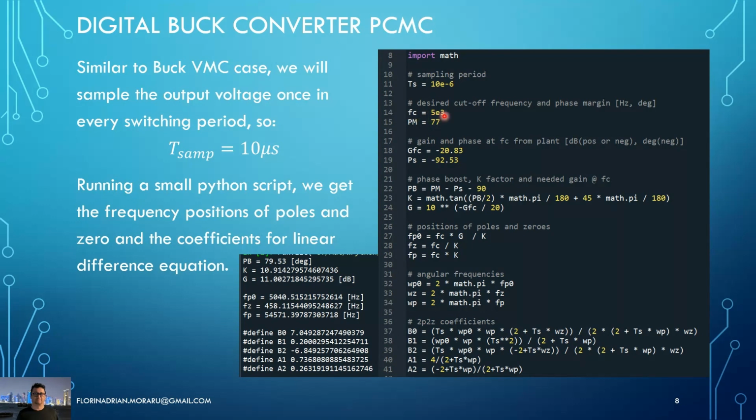And then we want a 5 kilohertz cutoff frequency and a phase margin of 50 degrees, but taking the worst case scenario with phase erosion. We saw it was about 9 degrees from the sampling and reconstruction process, and if we have a complete period time delay, then we have an additional 18 degrees, so in total about 27 degrees of phase erosion.